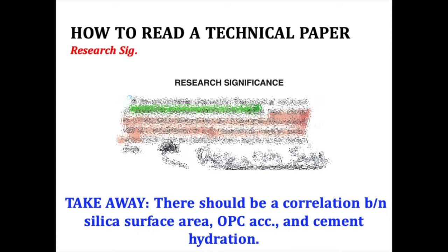And funny enough, when I was reading this paper, I was diving into my research with the U.S. Army Corps. I was just starting to get into the very same thing, but I was focusing on the impact of nanosilica size and surface area on alkali-silica reaction (ASR) mitigation, a more focused approach than this.